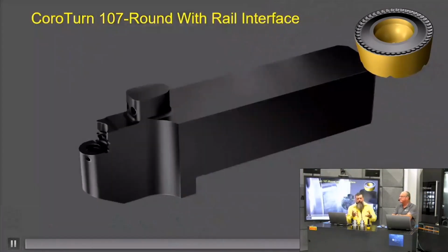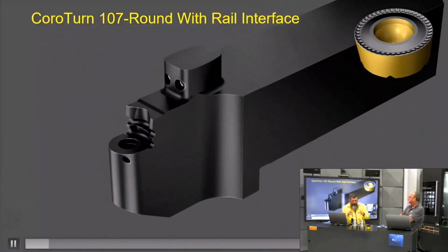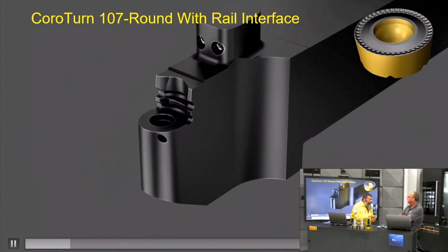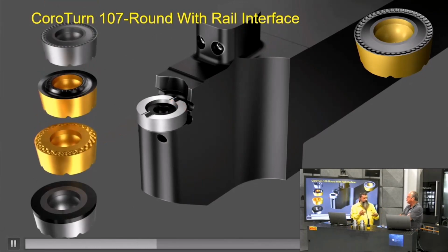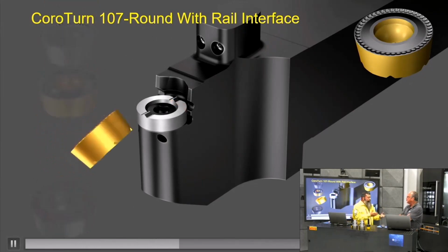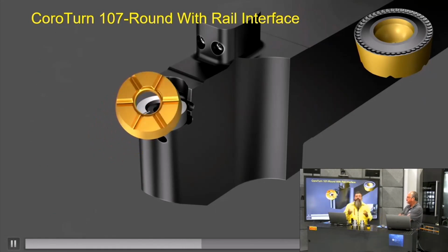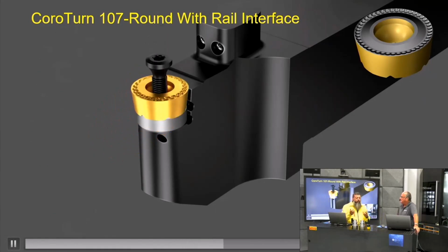So traditionally, Andy, people would think if I'm dynamic roughing or if I'm trochoidal roughing or if I'm using VoluTurn out of GibbsCAM, eventually this breaks down. And so this must not be a robust way to machine. But the reality of the situation is it's a very robust method. It's a very productive method.